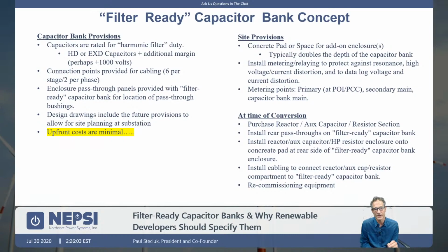And in this way, if you have a harmonics problem, you have the ability to do the design of the harmonic filter quickly. You don't need to send somebody out to take measurements. You're just going to call this device up over the network, over the internet, and download the data, and that will be enough data for a harmonic filter design guy to say this is the filter design that you need. So installing that metering is very important. It's a way to answer and address a harmonics issue very quickly.